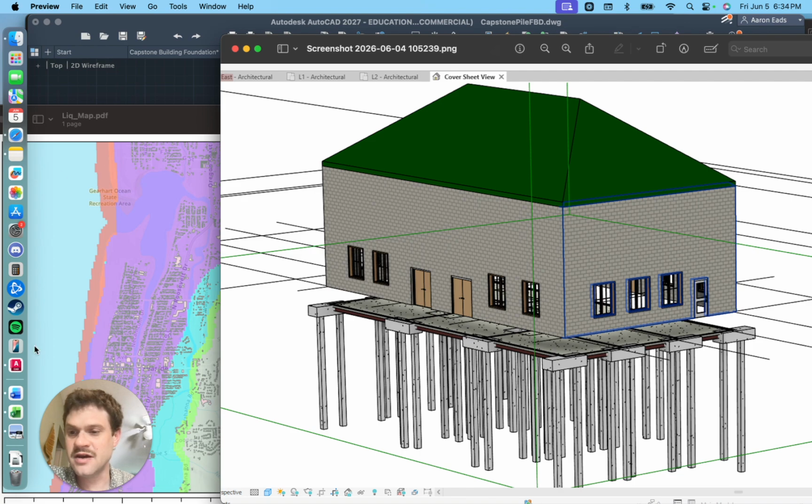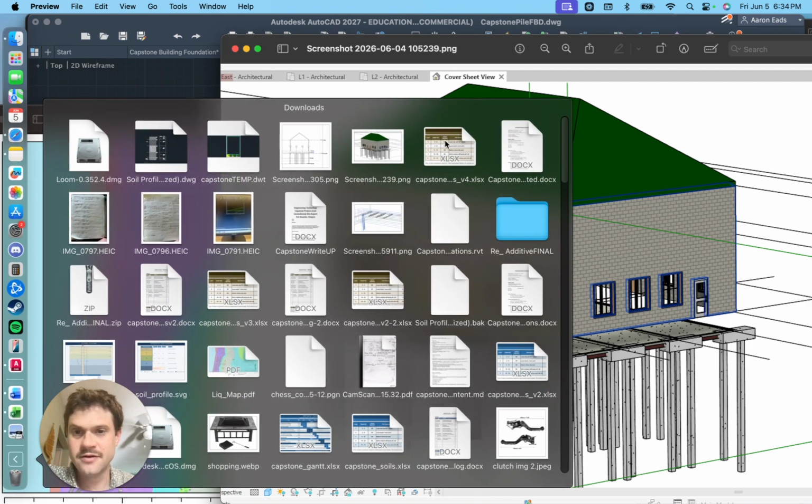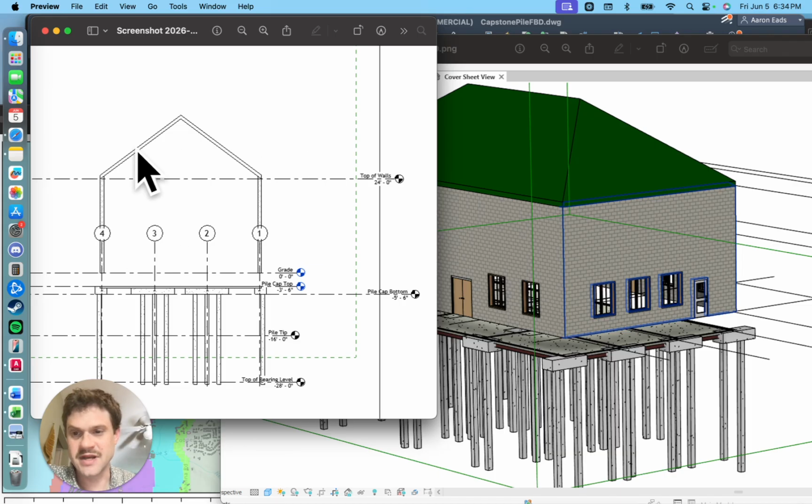And then I have another. This is another in Revit of the actual depth. So you're seeing here that the top of the bearing level is reaching the depth where it's hitting the dense, hard sand that will withstand collapse when liquefaction or an earthquake happens. This is meeting the requirements that this building will be safe in an earthquake.